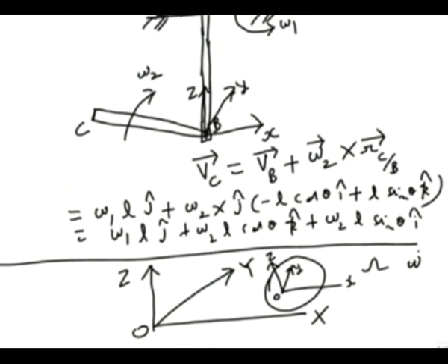So big omega and small omega in general can be different, but then you can easily prove one point, if I take the i axis about this and j about this other y, that I dot, the unit vector derivative, is equal to big omega, the angular velocity of the axis system, cross I. Similarly, j dot is equal to omega cross j.